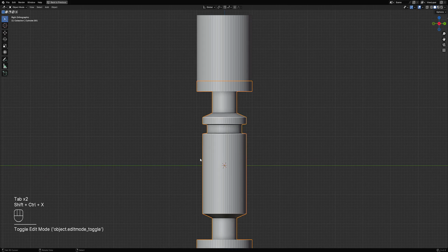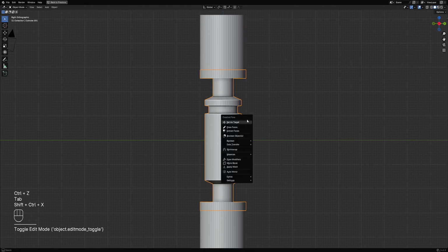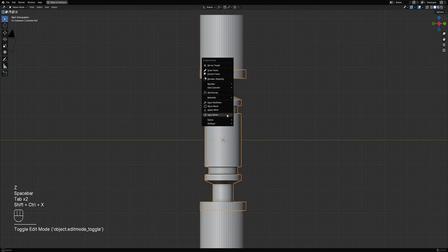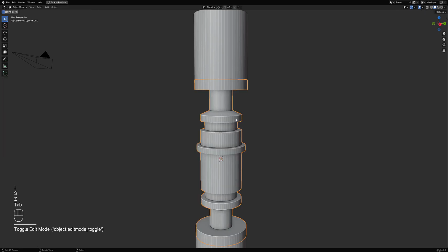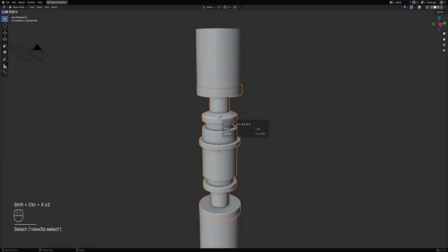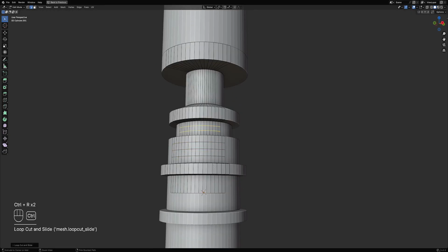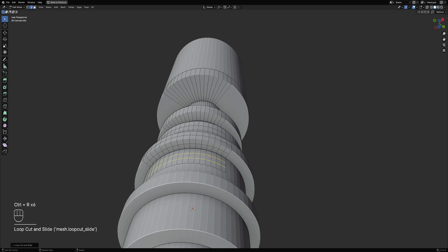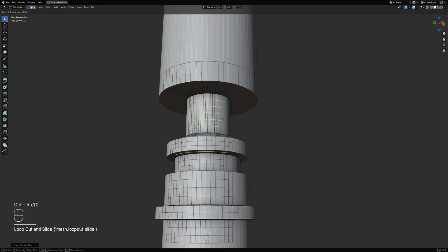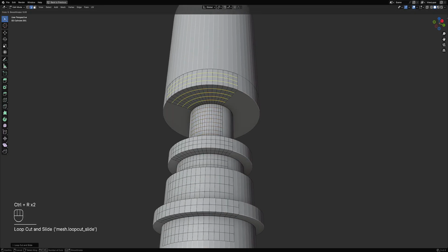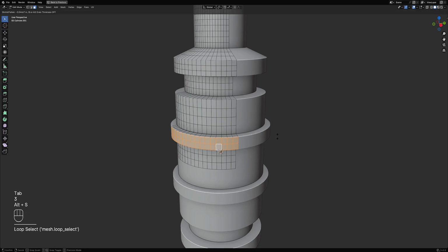Okay, let's not automate this first. I'm going to mark out the center and then apply mesh and do a bit more details. Now with all those extrusions, we need to reestablish the mirror and add more edges for the randomization, or edge loops to create more faces for the randomization. We shade it smooth, maybe make this smaller.